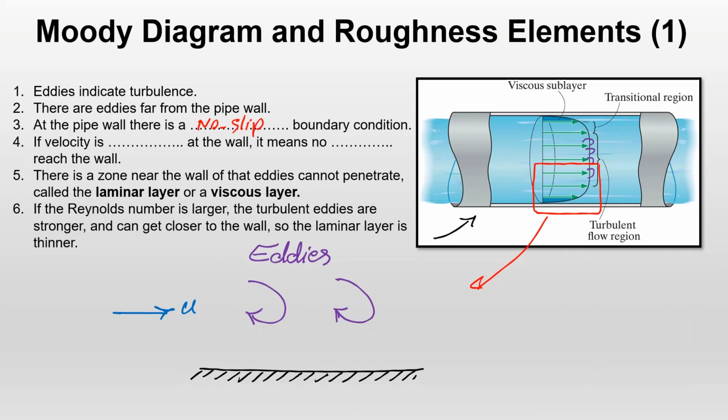Now you see, I think it was in the second class of this Engineering 368 that I introduced you to the fundamentals of the no-slip boundary. No-slip boundary means that whenever you have a particle very, very close to the walls of the flow, the velocity of this particle, the instantaneous velocity, I'm going to call it u0, is equal to 0, right?